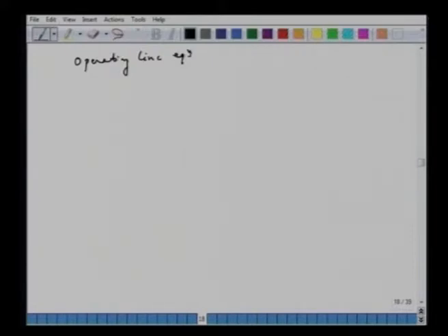So for the top column we have a general expression: y_{n+1} equals R over R plus 1 times x_n, plus x_T over R plus 1. If we choose the nth plate here, the vapor which arrives here has composition y_{n+1}, and the liquid which leaves the nth plate has composition x_n. So that's what the operating line does.